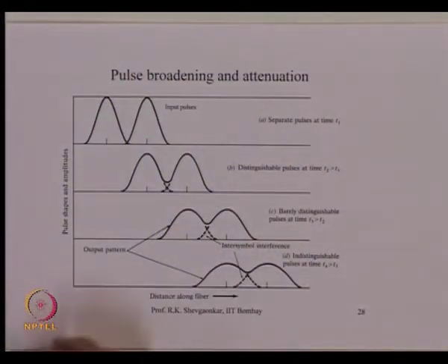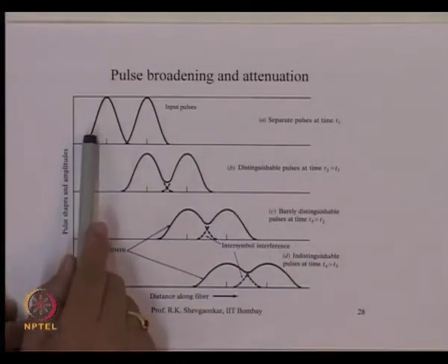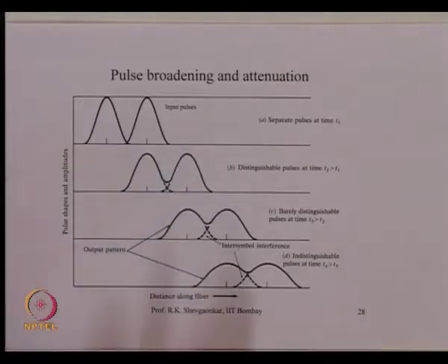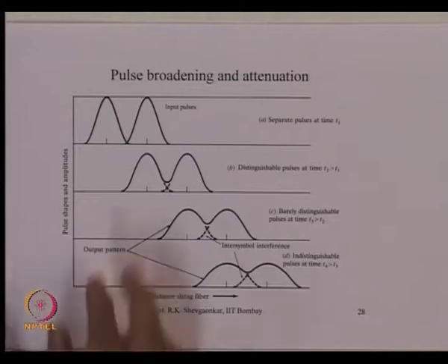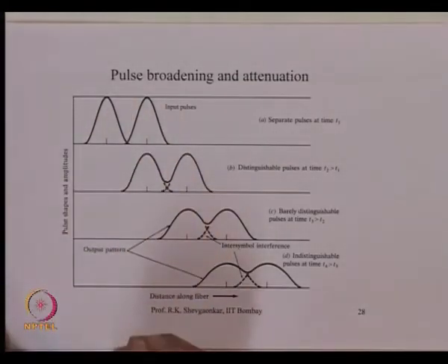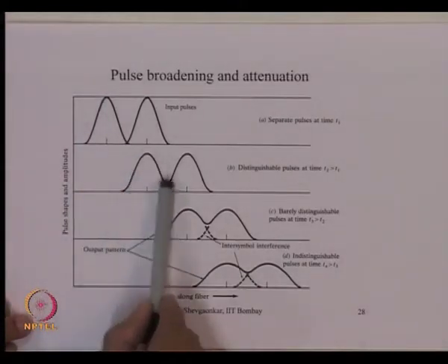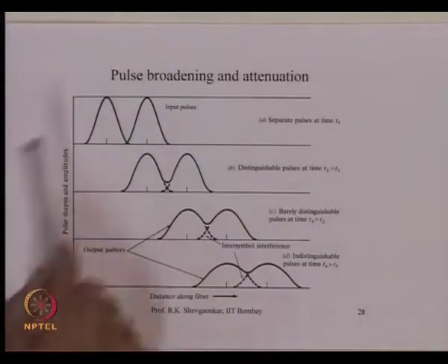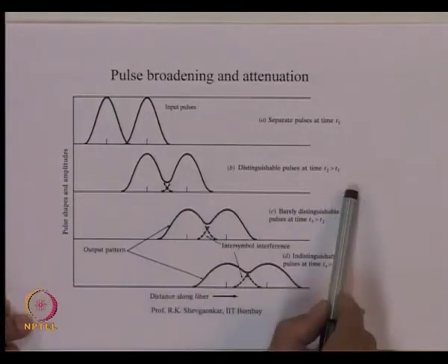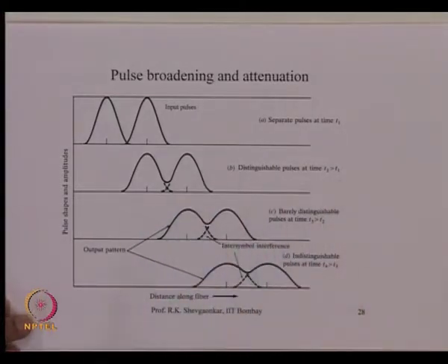So, if we send a signal in the form of pulses, what dispersion means is, as the signal travels on the optical fiber, the pulses get broadened, and here we are not even talking about the shape of the pulses, we are not even saying the shape of the pulse is retained or anything. We are saying if this pulse was representing a presence or absence of a bit, then as the signal travels, essentially this function broadens because of the phenomenon of dispersion, and as it travels more and more, the broadening becomes more and more.